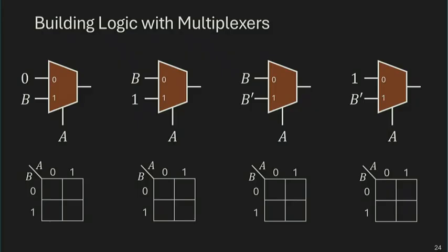All right, I'm afraid time is up. And then I'll do this on the board together with you. So you can think about its behavior in terms of a 2x2 K-map or 2D truth table. When A equals 0, output will be 0. When A equals 1, you look at this column, output is B. So B is 0, output is 0, B is 1, output is 1. And that's really an AND function. So you get A dot B at the output of the mux circuit.